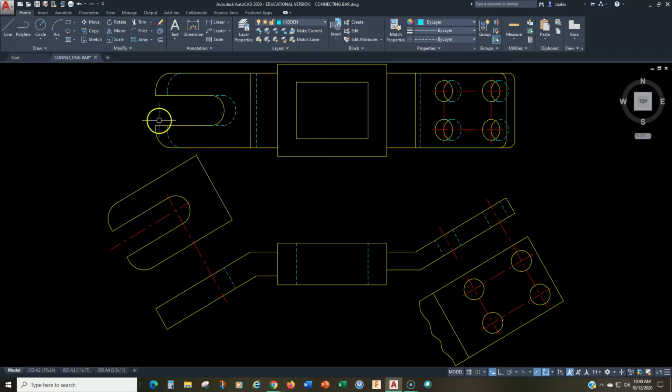A couple things here. You'll notice that in the top view we have these hidden lines because these are full views, not partial views. We have elliptical holes, partially hidden, and that's part of the difficult bit. In the front view, it's not as difficult to understand, with the holes there and the slot there.